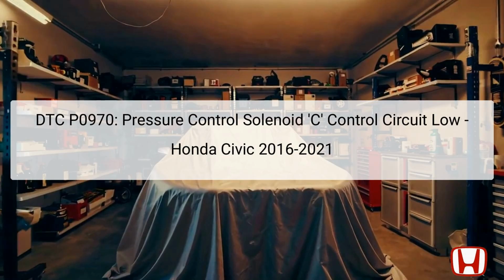The solenoid operates based on a duty cycle output from the transmission control module, TCM, that manages vehicle hydraulic functions. If the TCM perceives that the current flowing through the solenoid doesn't match the expected value based on the commanded duty cycle, it records this anomaly and triggers the P0970 code.